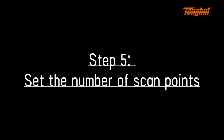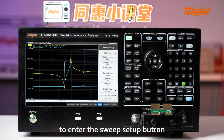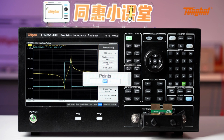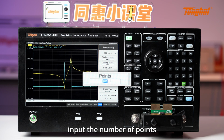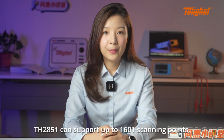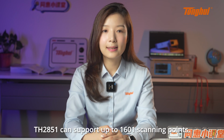Step 5. Set the number of scan points. Press Sweep Setup on the front panel to enter the Sweep Setup menu. In the input box of the scanning points button, input the number of points. TH2851 can support up to 1,601 scanning points.